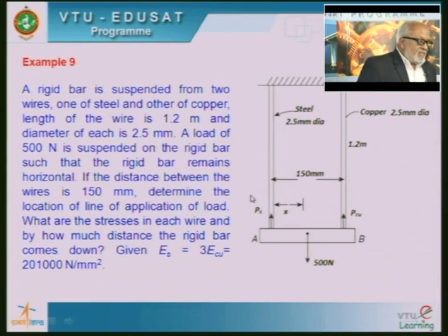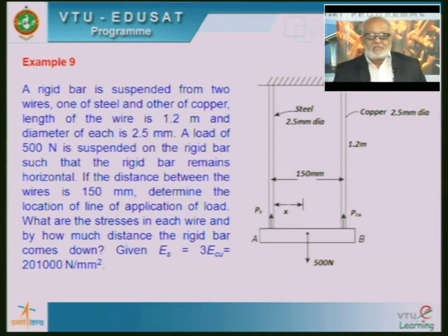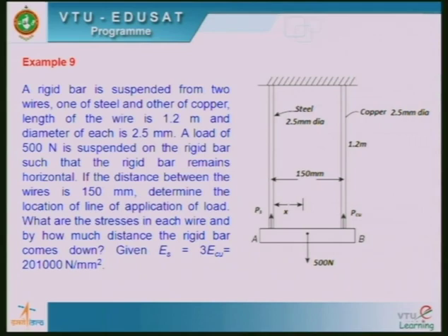Next, we solved about two problems today. In the seventh problem, it was mainly with respect to two aluminum flats with one solid bar, that is a steel solid bar. We found out the stress in steel and the stress in aluminum. In the second problem, it was a sort of an encased section. We have a steel tube outside, then inside we put concrete, and now we are going to calculate the safe load such that the stresses in concrete and steel are not exceeded.